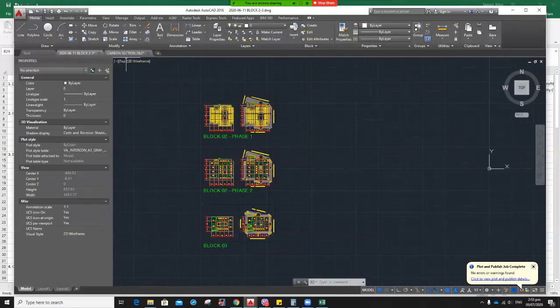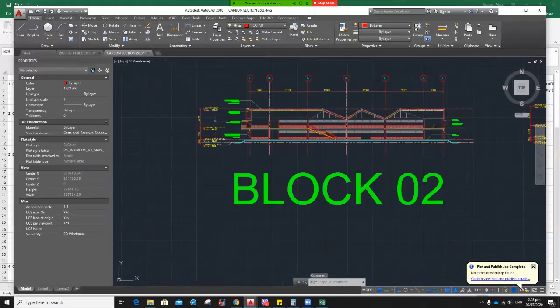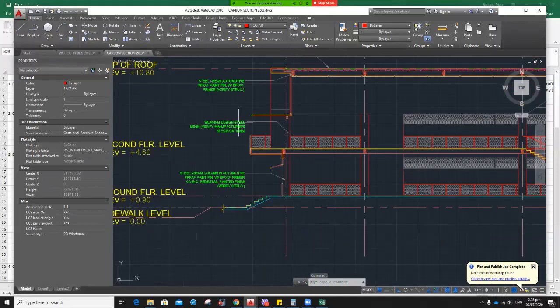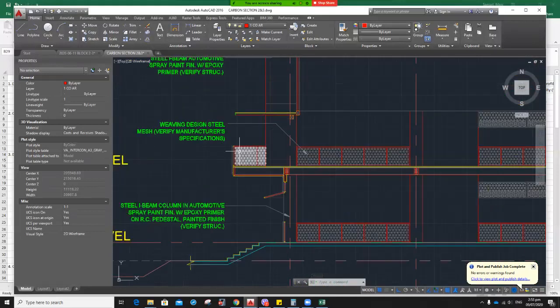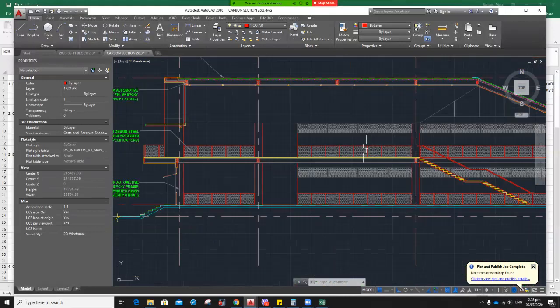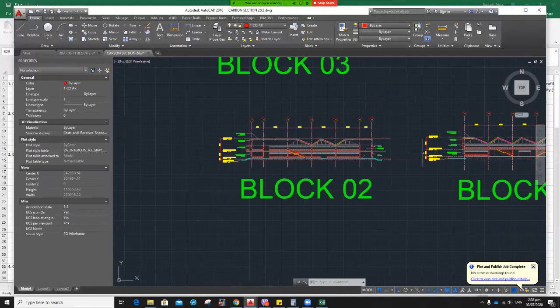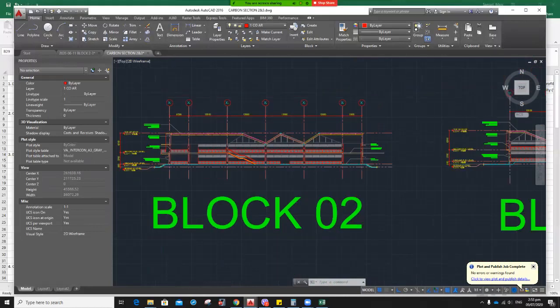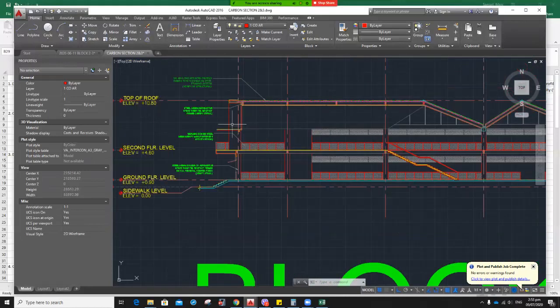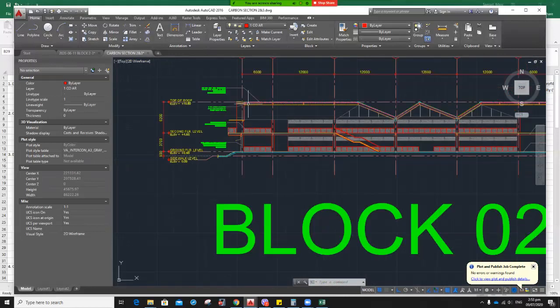So this is the premise why we can just ignore it for the building frame, because the structure is open, so there's very minimal wind that we will be experiencing for the framing of the structure. But for the roofing, we really need to consider the wind. Okay, so that's it.